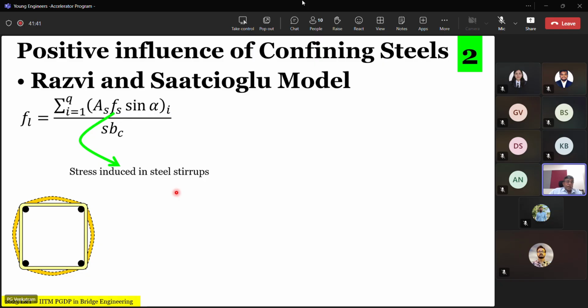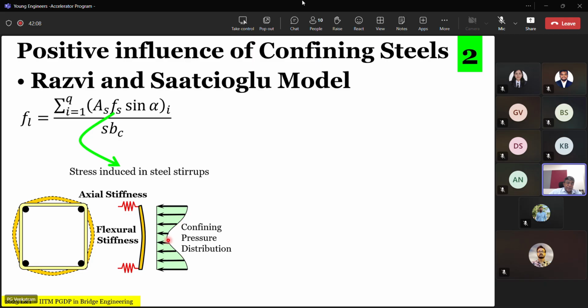Okay. So if you take a look at this, you will find that this is the kind of confinement you see. The flexural stiffness of the bar also becomes important. Flexural stiffness of the bar and axial stiffness are quite related, because they depend upon the section sizes. So you can't have a differential understanding of it. You will notice that due to the flexural stiffness, there is less confinement at this place and more confinement at that. And this tells you that if you want a more uniform confinement, you reduce the spacing of these transverse bars, the distance between the ties.